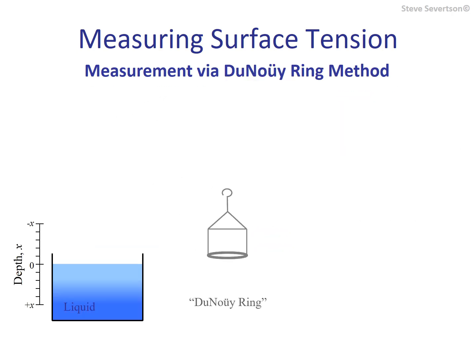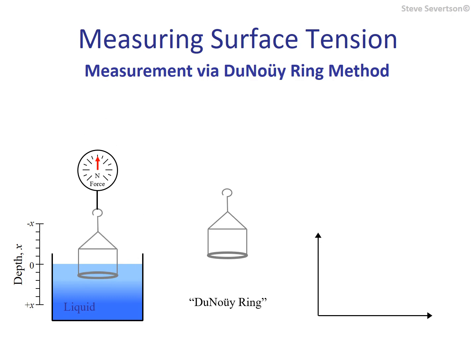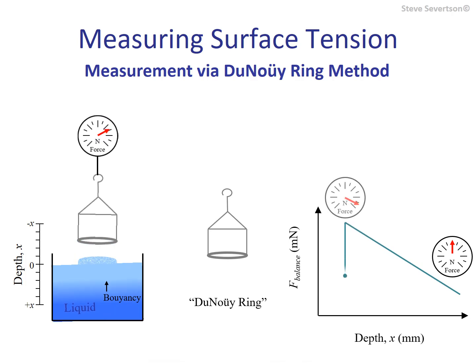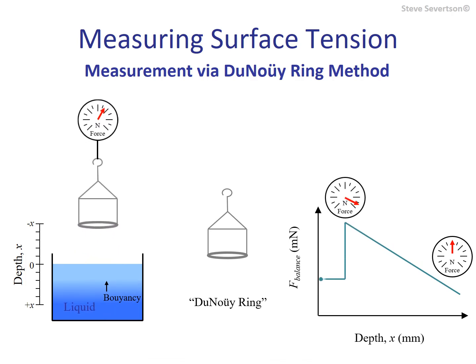Another popular direct measuring technique of surface tension is the Du Noüy ring method. The same principles are at work as described for the Wilhelmy plate experiments, but the technique differs in more than just the test sample's geometry. Here we begin the test by fully submerging the tared ring into a test liquid, and during measurements, it is pulled back through the liquid surface. We calculate the surface tension from the maximum force measured during this process.